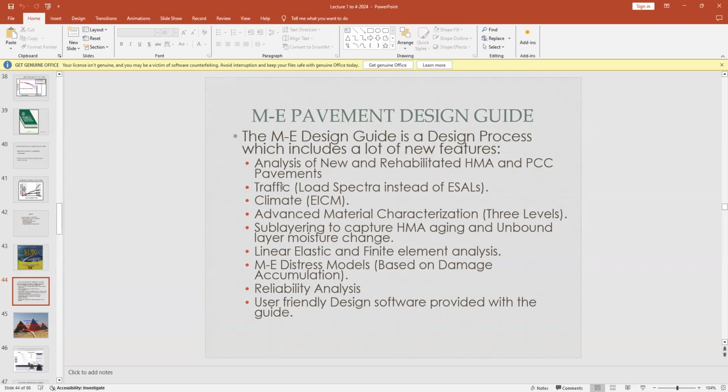Sir, if you refine it further, like you said they refine it in another factory, it will be costlier than the rigid pavement as well. No, it's not like this. The difference between rigid pavement and flexible pavement is around 7 to 10 times. With all that processing, it will be maybe 2 or 3 times costlier than the ordinary asphalt pavement. It will not be 7 times.